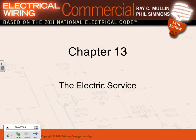There's the service conductors, service entrance conductors, service point, overhead service drop, overhead service conductors, underground service conductors, and service laterals. All this terminology that I threw at you when it comes to service. Then you land them in a service disconnect, and from the service disconnect, you put a switchgear or a switchboard or a panel, and you feed all your feeders and branch circuits from there. You're going to see when you look at the picture, it's going to be very clear.